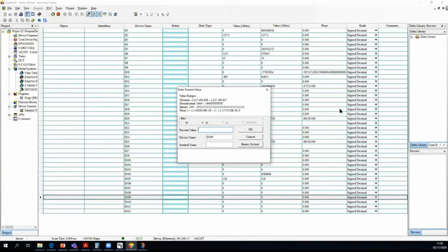Currently the drive is set for a 2500 pulses per revolution encoder. That means the drive will actually count 10,000 per one revolution, for every pulse rising edge and falling edge. So if I want the drive to do one rotation, I can just set it to 10,000.